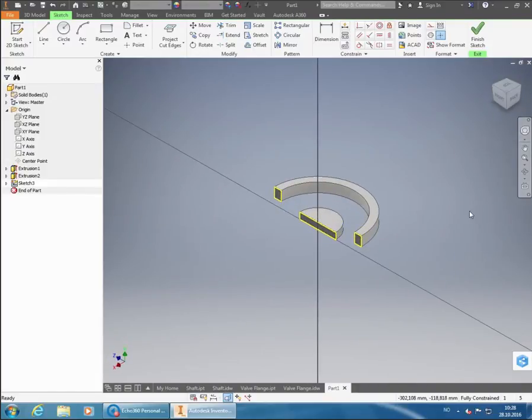I'm just going to flip it a little bit here to show you something. Along this sketch, we are going to create the outline of one of the spokes, and then we're going to extrude it symmetrically in both directions, so that we are basically centering it on this plane. But when we are extruding it then, we have a problem here because the curve of the disc is moving away from our extrusion, which means that we're going to have to make the outline of our spoke go slightly into the disc. So that we need to move it a little bit inside the disc so that it's going to be fully covered by the disc after we have extruded it.